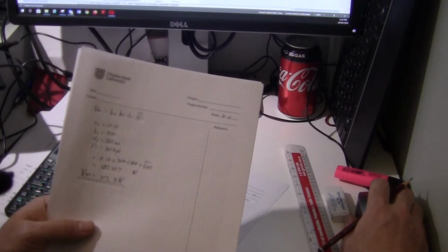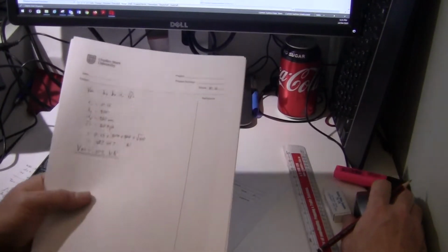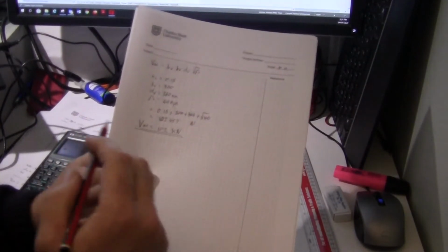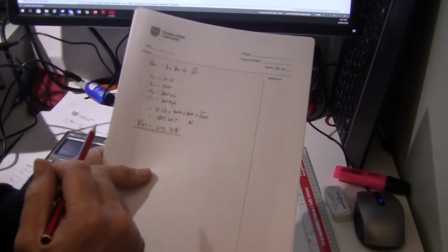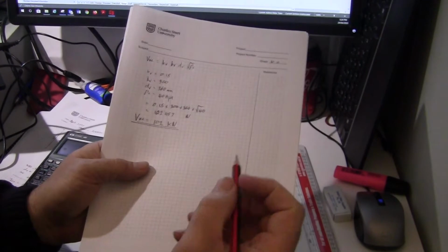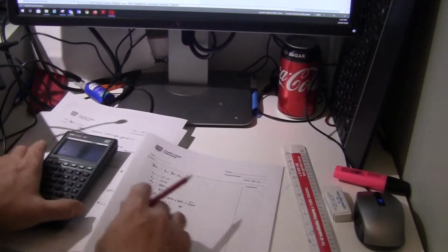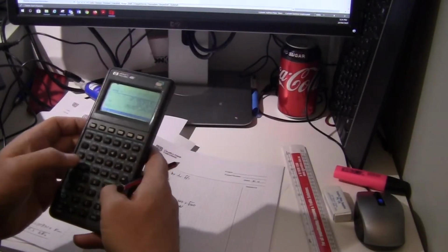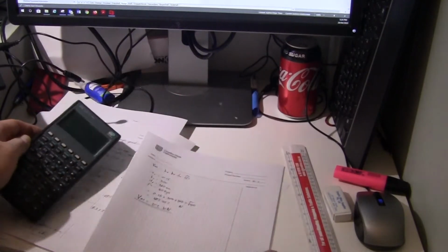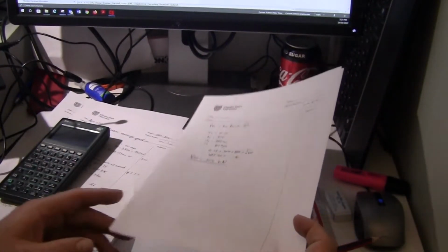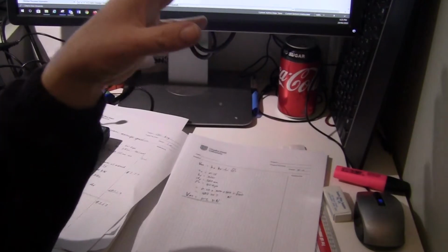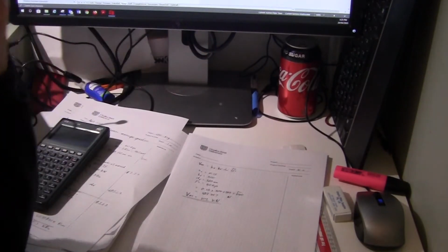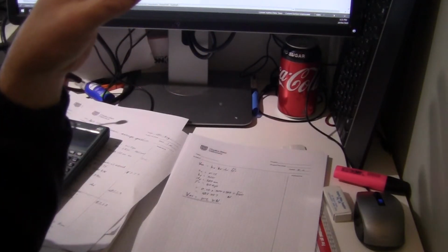All right. So you recall earlier that if our shear load was less than 0.5 times that, you don't need any shear steel at all. So if our shear load was less than 0.75 times that, which is 76.8 kilonewtons, and there was no torsion, you would not need any rings in this beam at all.